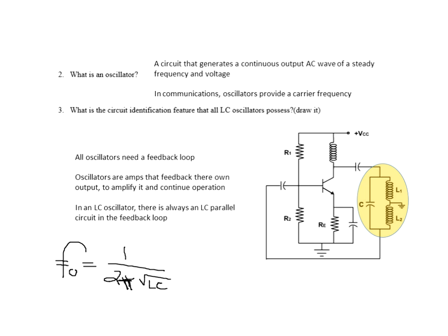Okay. Now, oscillators don't have an input. Here's a common emitter amplifier. I have an input and an output. Input on the base, output off of the collector. A common emitter amplifier can be used as an oscillator, but we have to take part of its output and feed it back to its input.